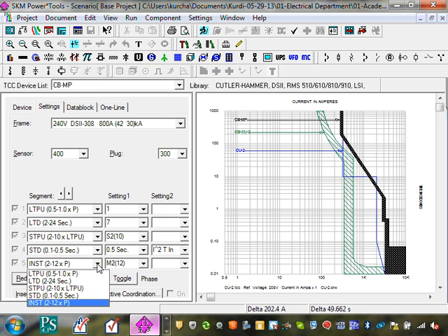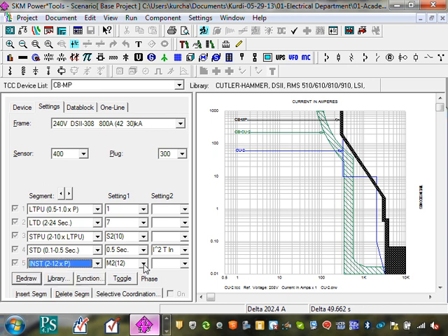And the last one, this is for the short circuit. This one is long time, this is the short instantaneous. That one's called instantaneous. If all hell breaks loose, and I have a bolted 3-phase short circuit, I want my circuit breaker to trip at, it's set at 12 now, so 12 times the pickup times this.